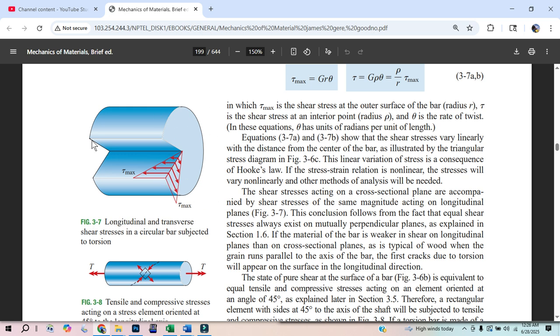Cool. So then even there, if I know the length of this cylinder, I know the angle of twist, and then I can work backwards. If I twist a cylinder and it gives me a certain angle of twist, I can figure out what that circumferential distance is. I can know the length and that distance, know that this is a small angle, and find that angle.